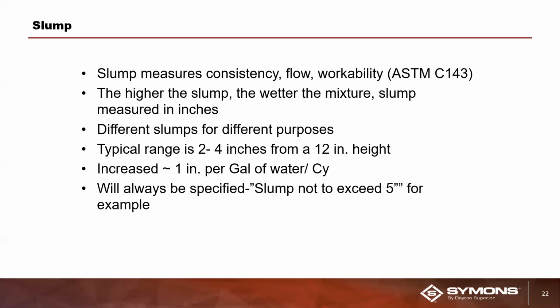The specified slump will not exceed 5 inches, for example. That is always the example that you want to have. Once you get above 5 inches, the material is really just going to flow, and it's going to take a little bit longer to cure out. And the one problem you do have at that point is you may start to get aggregate that's going to separate from the liquids in the concrete.